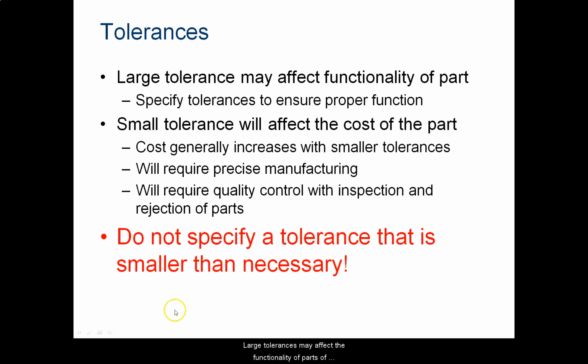Large tolerances may affect the functionality of parts. Having something be too big or too small might make them sloppy, so it's too loose of a fit, if you're talking about two pieces that are supposed to snap fit together.